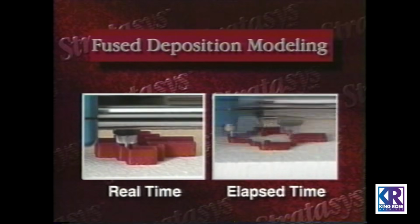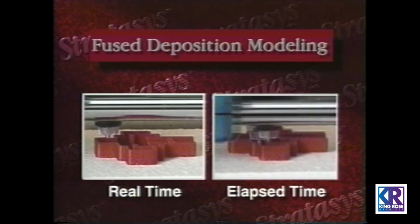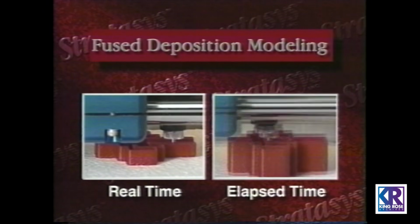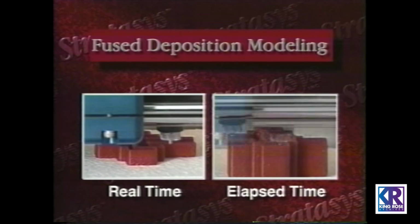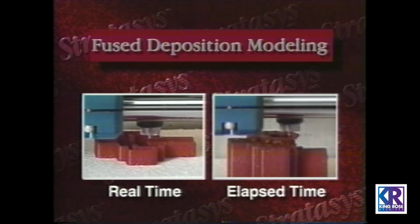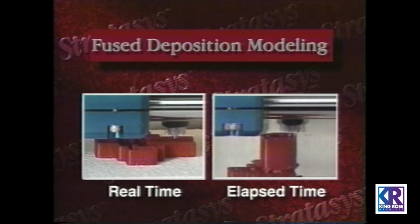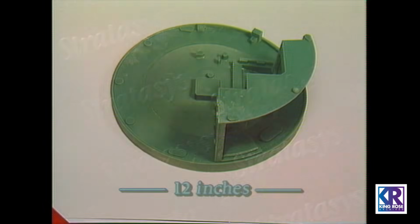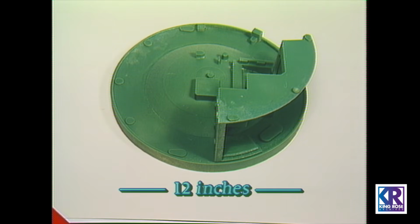Since it is only slightly above the melting temperature, the wax quickly solidifies after joining to the underlying layer. When a layer is completed, the supporting table lowers and the process continues with the next slice. After the final layer is deposited, the part is removed from the table. The selective laser sintering process is already being incorporated into Sandia's production of prototypical components. This wax pattern was produced entirely from an electronic design.